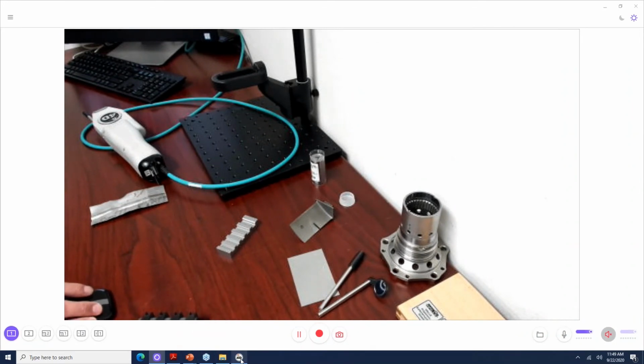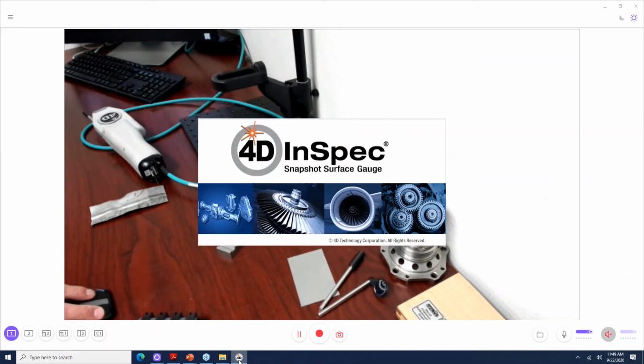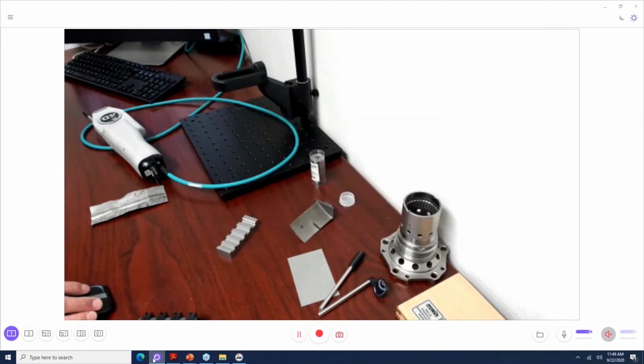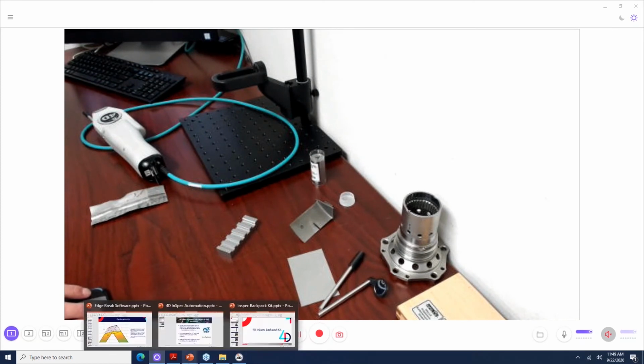If there's multiple pits within the field of view, you can measure it, or even if there's a large dished area, you can measure that. It will calculate each of the corrosion pit depth, area, overall corroded area, because some parts have a, say, 10% limit on the amount that can be corroded no matter what the depth is. So that also can be calculated.